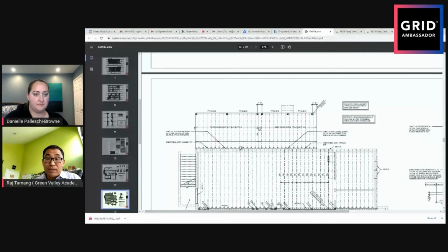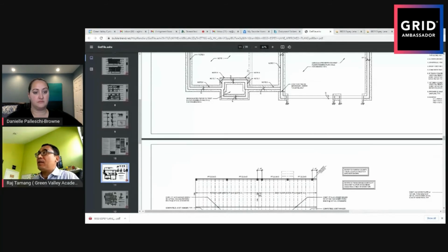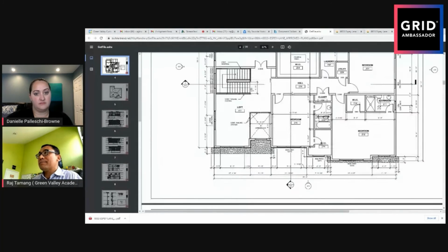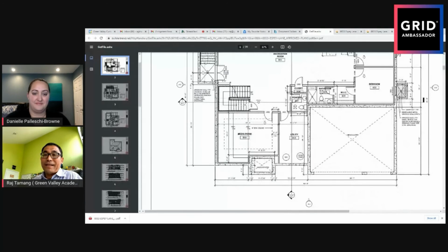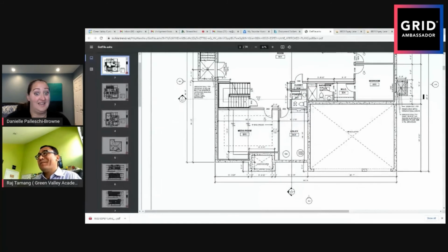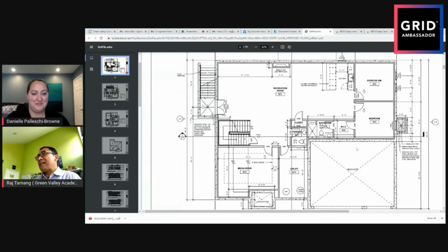You only show framing information, but for all the related dimensions, you have to go to the architectural. For building height, grading, or outside elevation, you have to look at the grading plan, civil engineering. So those are all related. All these documents, you have to review carefully. If you do take the time, it's going to save your life, headache, and money, right? So a lot of time, life, headache, and money. Exactly. So like I said, make sure that all the window openings are there.